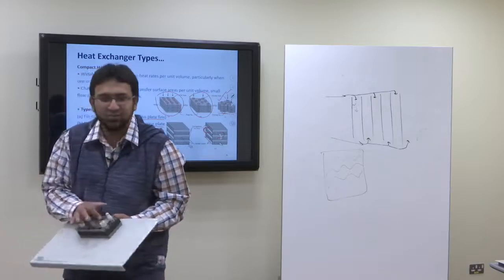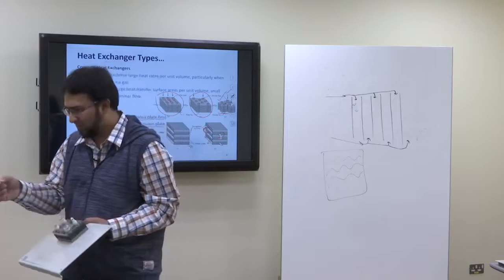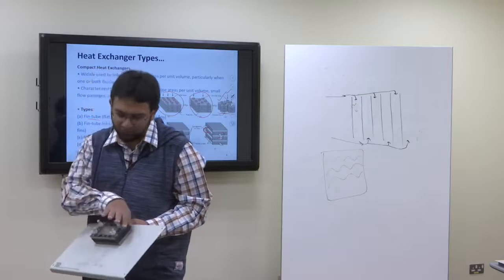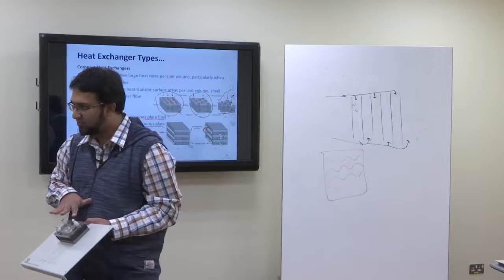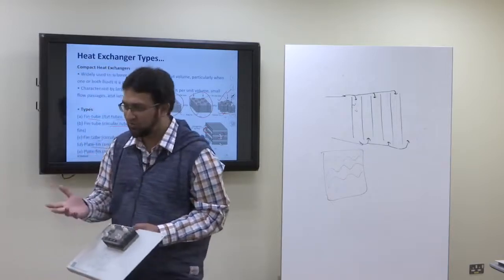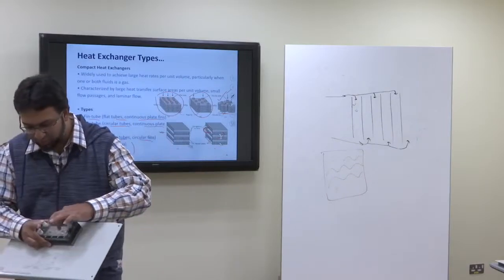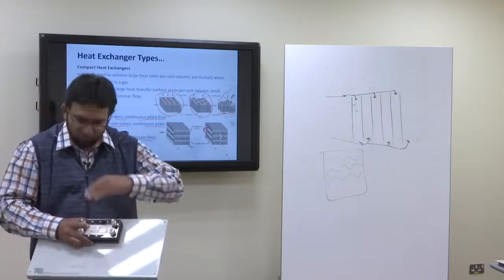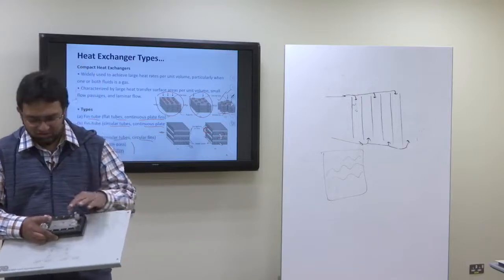They will add a little more heat transfer area, but the amount of addition of heat transfer area is very minimum. The larger objective is the turbulence. You don't want the flow to be smooth as it passes through the plate. You want the flow to be a lot turbulent. So how to produce turbulence? Right now, they have put here just small strips on the plate, and these strips are present on each plate, on each side. But in reality, this is just to show here.